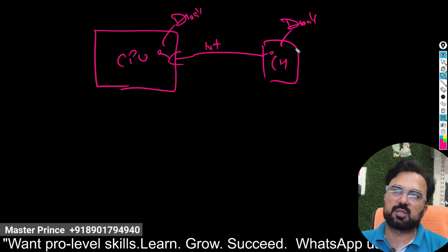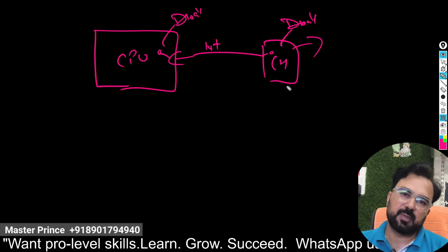For testing you must remove this charging IC, because there is no other way. After removing the charging IC, put one probe on ground, the black probe, meaning reverse bias, in diode mode, and you get a diode value here.